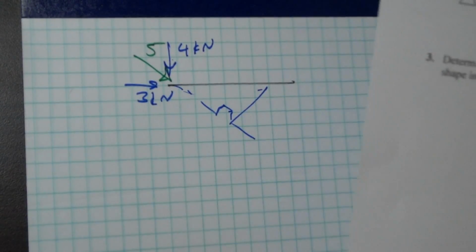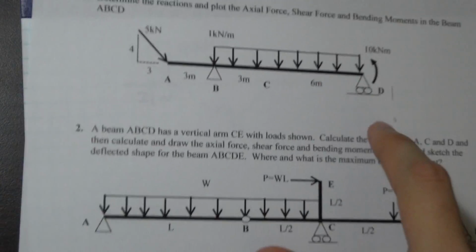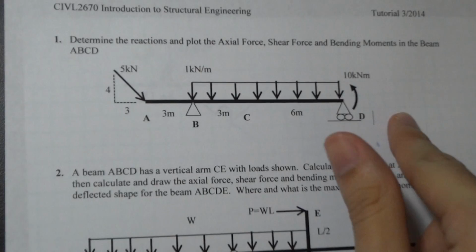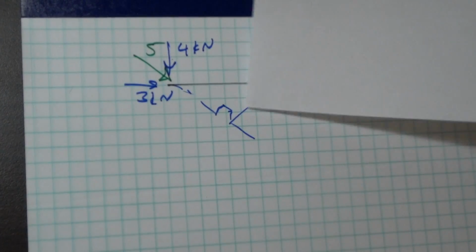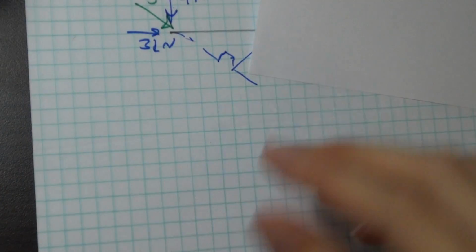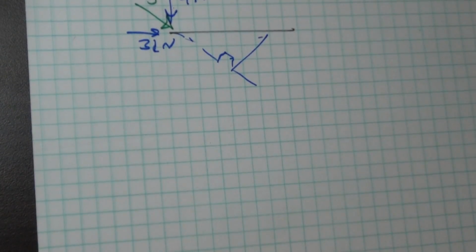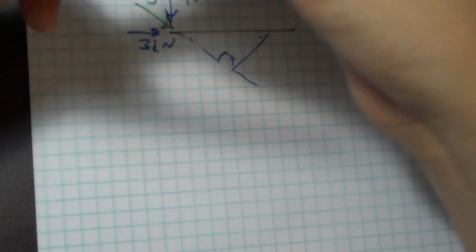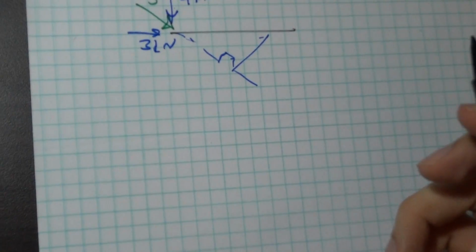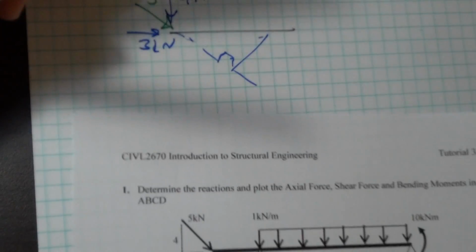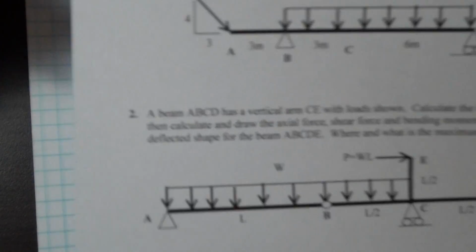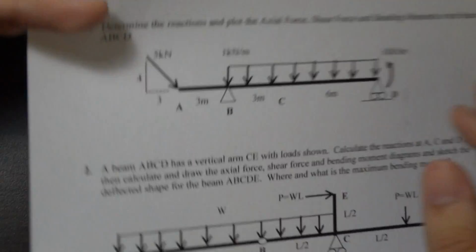The next step is finding the reactions. Finding the reactions in general is usually pretty straightforward, but the tricky thing with this one is the applied moment, and usually this is where I see people mess up. You only see the applied moment when you're using your moment equations. It will influence your reactions, and that's why I'm going to calculate one of your reactions for you. Just make note of these values. You should have this in front of you somewhere.